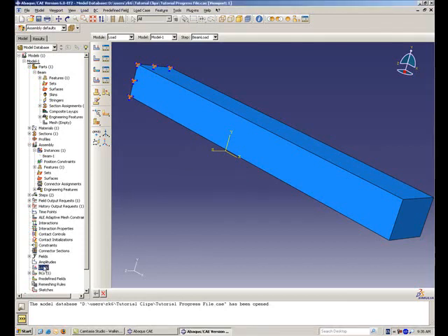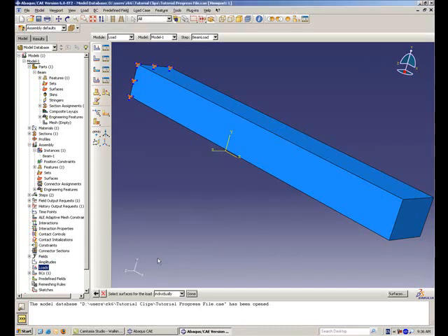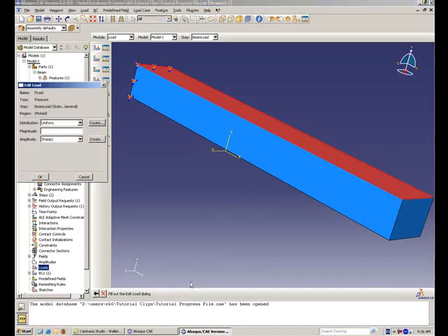Now you can apply the load on top of the beam. Double-click Loads in the model tree and name the new load Pressure. Select Beam Load as the step in which the load is applied. Accept Mechanical in the category list, and choose Pressure in the Types for Selected step list. In the viewport, select the top of the beam as the surface where the load will be applied. Hit Done in the prompt area, then enter a magnitude of 0.5 for the load.